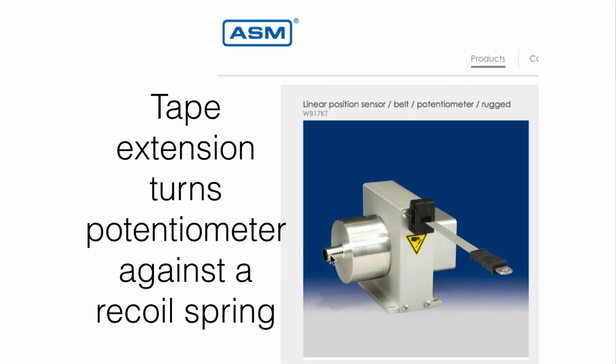And if you take that potentiometer, put it in here, here's a high precision potentiometer, and add a tape like this, a precision steel tape with a recoil spring in there, then as I pull out this tape linearly in this direction to detect linear motion, it'll rotate this potentiometer, and I can use that to translate into a linear position based on the rotational position of the potentiometer. And these are quite commonly used devices for measuring linear position, for instance, as mechanical elements move back and forth along some known distance.